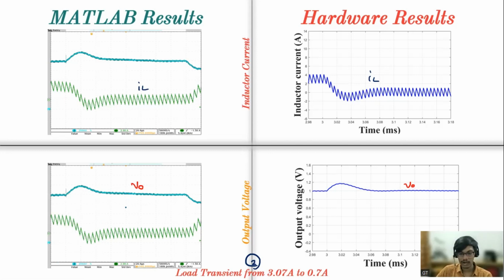If you directly go to the hardware and something goes wrong, any device might get damaged, and you have to replace the device, which we want to avoid. So we always check in the simulation first, make sure everything is working perfectly fine and our logic is good, and only then move into the hardware. We can also get some idea whether our logic is working according to what we had thought in the beginning, whether it is reaching within the settling time, and whether the undershoot and overshoot are within our range or not.